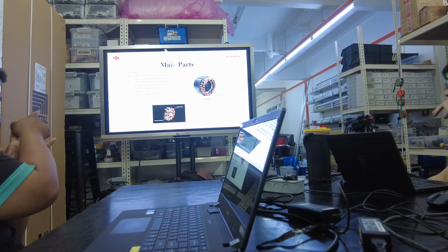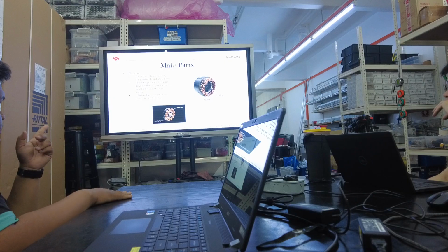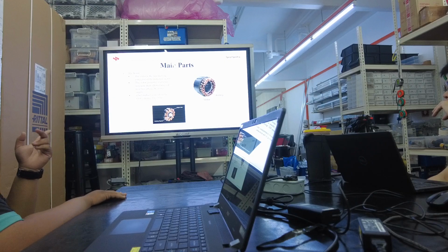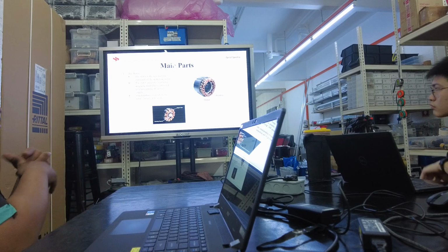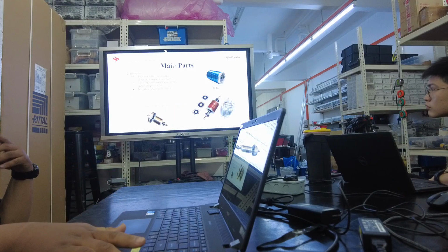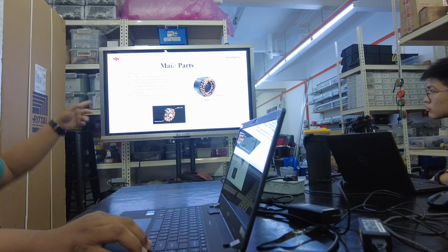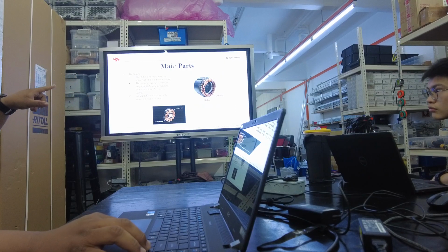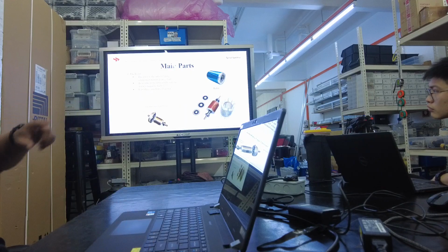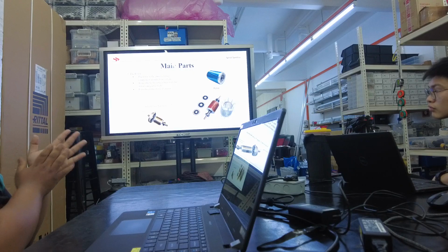So basically the stator generates a rotating magnetic field when connected to a three-phase AC power supply, and then it induces current in the rotor, causing it to rotate. So what makes the rotor rotate is actually the stator that produces the magnetic field, which then affects the rotor to rotate, and that will create the mechanical energy.